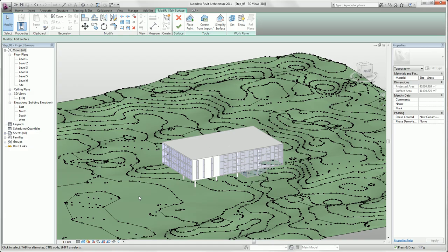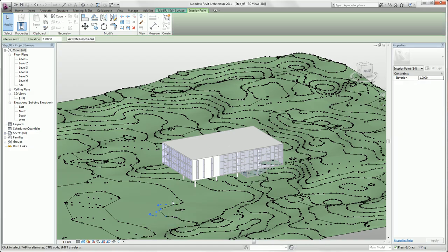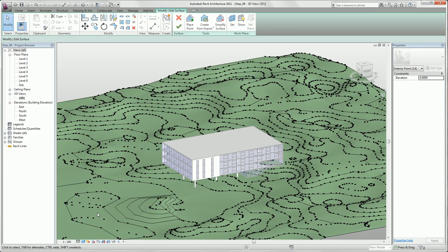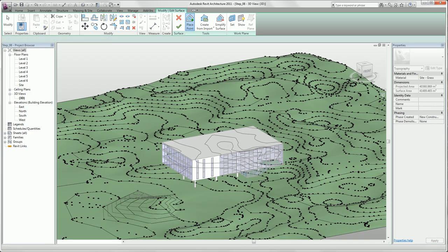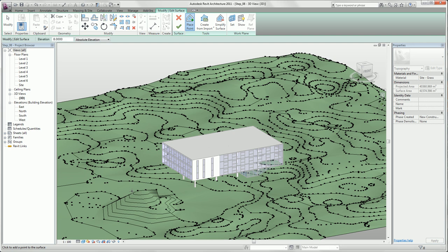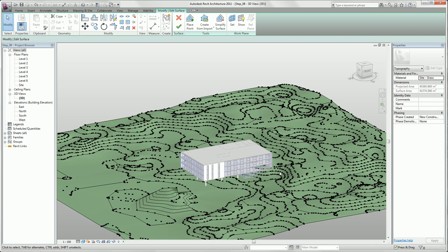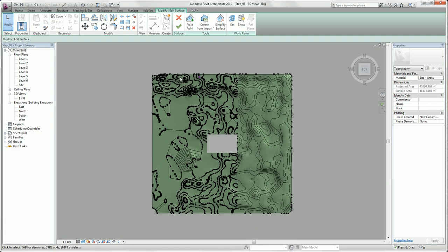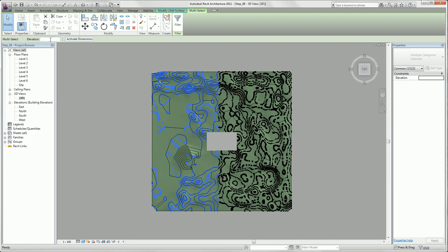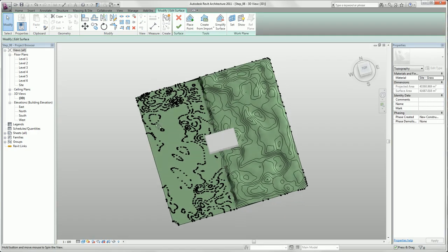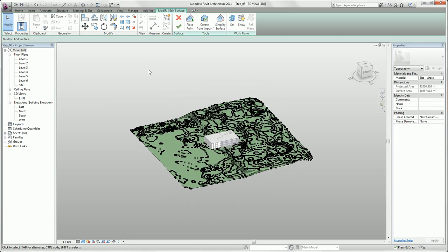So if we select several points and give them a height of approximately 4 meters, our site changes, and we can also place single points. We assign a height of 8 meters, and we can place them on the site. Now we want to flatten half of our site, so we switch into the top view. Select more or less half of our points and assign a height of 0. If we move in our orbit, half our site has been flattened.